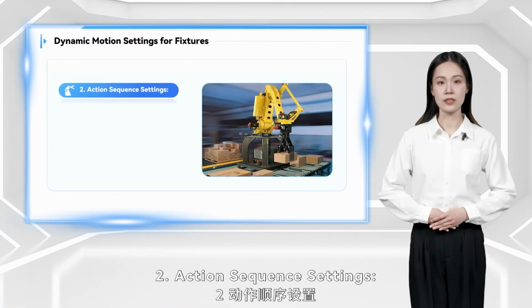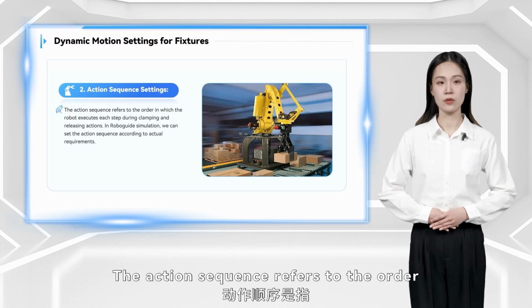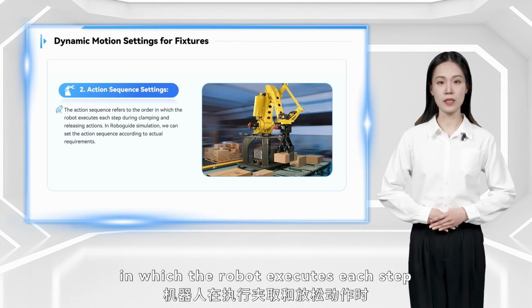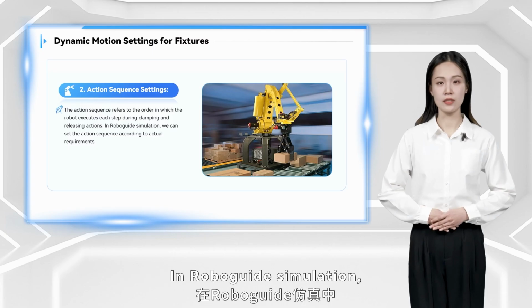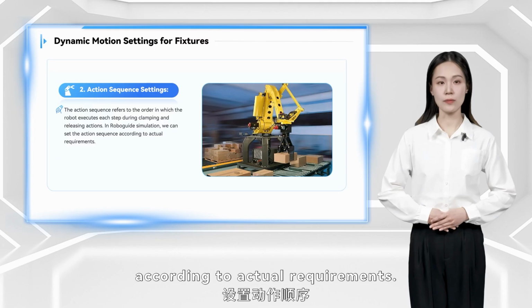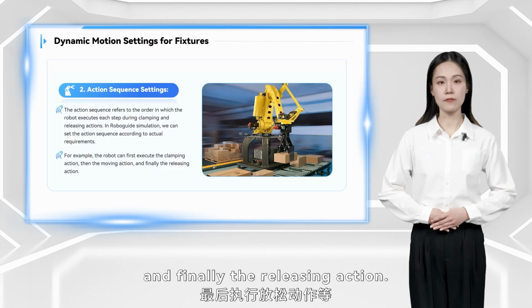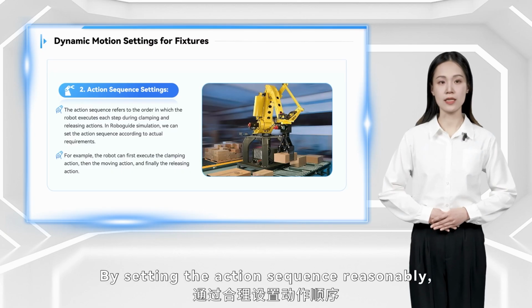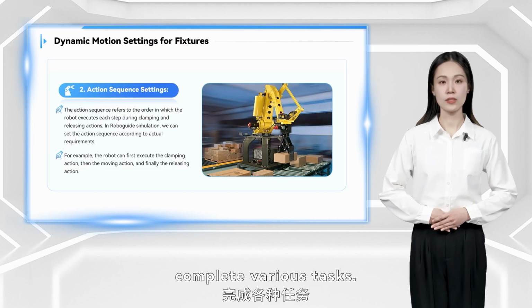2. Action sequence settings. The action sequence refers to the order in which the robot executes each step during clamping and releasing actions. In RoboGuide simulation, we can set the action sequence according to actual requirements. For example, the robot can first execute the clamping action, then the moving action, and finally the releasing action. By setting the action sequence reasonably, we can ensure that the robot can efficiently and accurately complete various tasks.